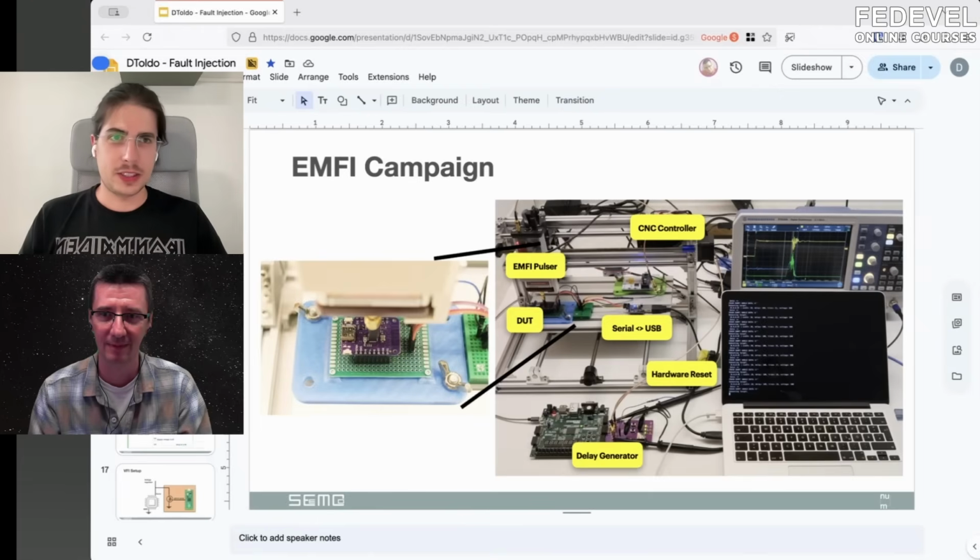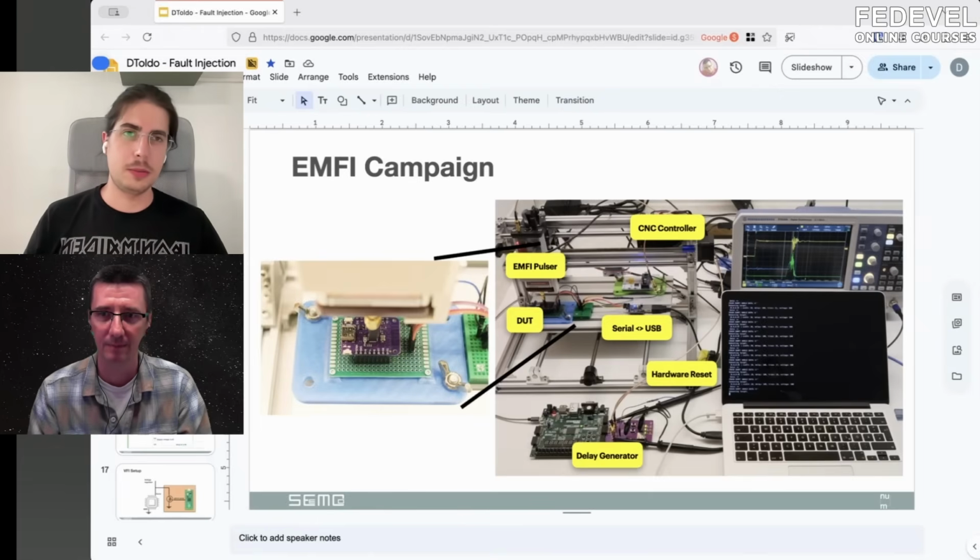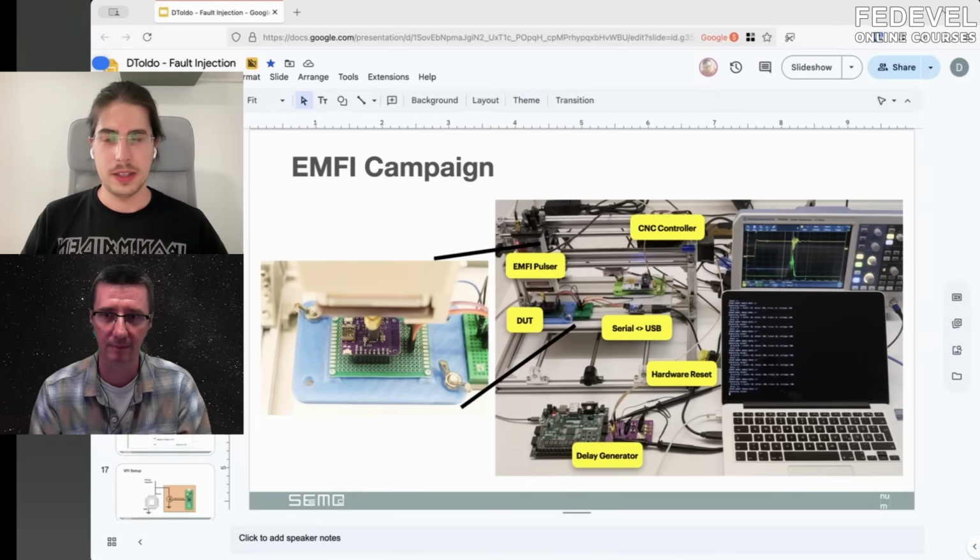Basically, anything that's checked in software, even hardware fuses, needs to be checked in software. So everything that can be checked in software can be attacked from the outside, from the hardware side as well. And it's important to know because a lot of people will put big assumptions on features like secure boot or hardware fuses because it sounds like hardware is secure, like something you cannot exploit like a software bug. But in reality, by having access to the hardware, you can change the control flow of a program running on an embedded device. And therefore, you can circumvent lots of security measures.